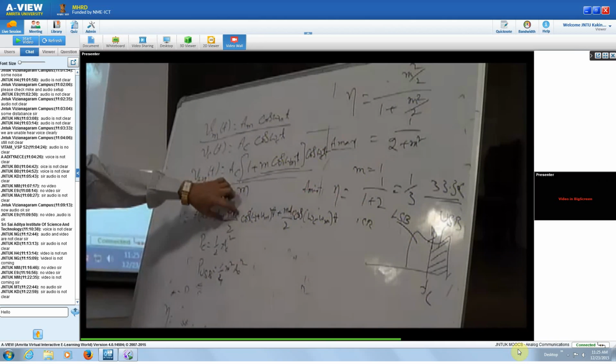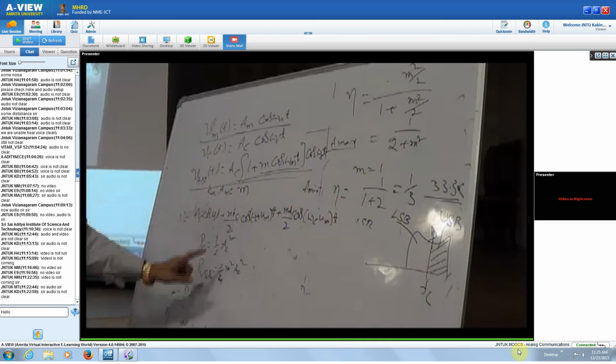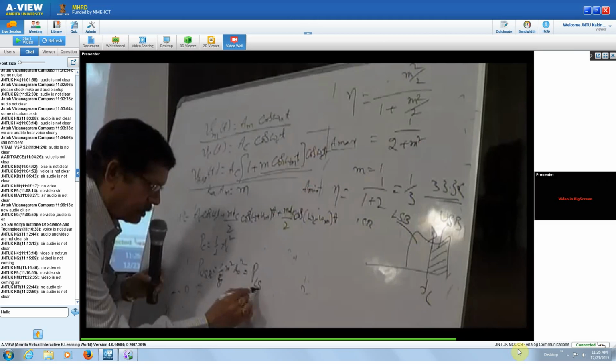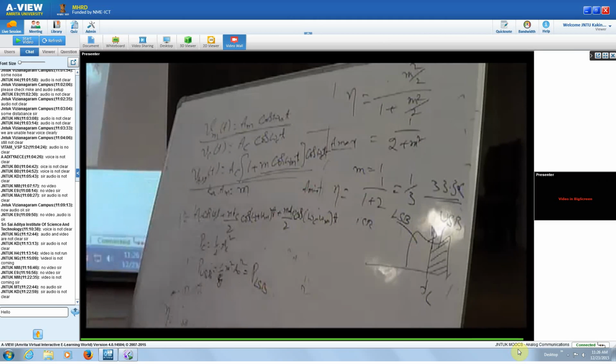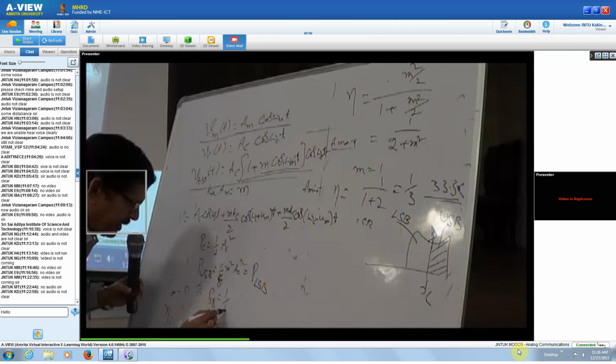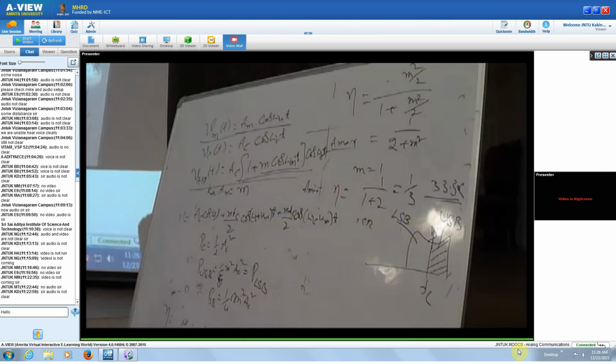So this square by half, because this is a sinusoidal signal. So m square Ac square by 4, by 2. Therefore, this is going to be 1 by 8 m square Ac square, and this will be equal to your lower side band power also. Therefore, your total side band power will be 1 by 4 m square Ac square.